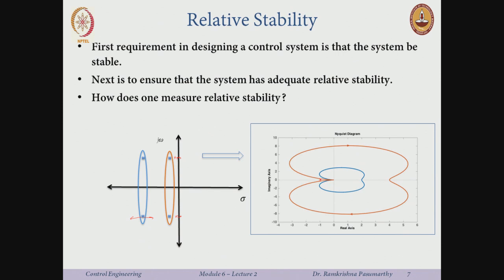Okay, now let us come back here. So, what is the point of interest? As long as P equals 0, say the open loop system is stable, I just want Z to be 0. And if Z is 0, Nyquist tells me that the system is stable. Now, who decides this? This is my guard, who says, well, you cross this line, you trespass, and you become unstable. So, the idea would be, I will just stay as far as possible from this point -1 plus j 0. Look at the blue line here, it starts here and goes here.